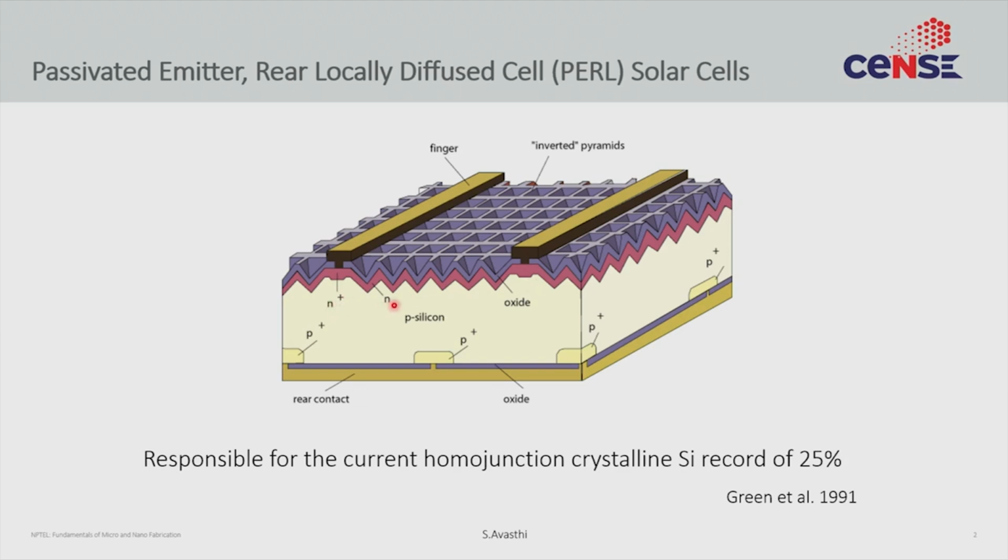So there is a moderately doped diffusion, and then we need a second diffusion to do the highly doped diffusion. And of course those two are happening at different places. So we probably need to do lithography in the middle, right? So you need two lithography steps.